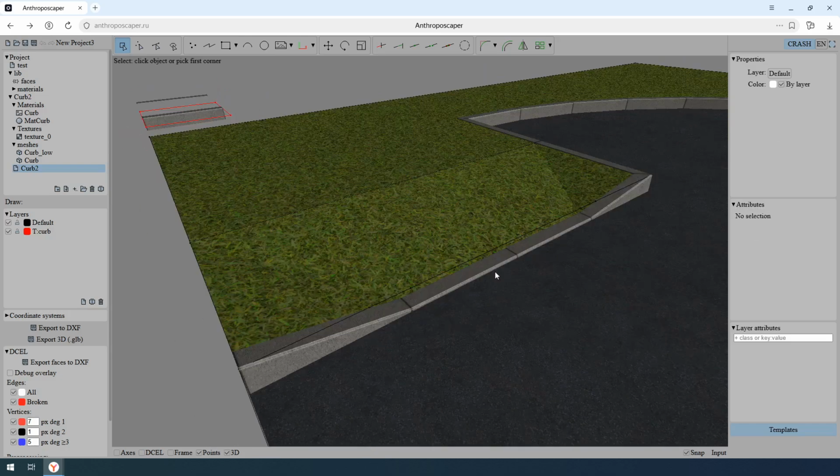One more touch, this time about lighting. Let's look closely at the spot where the descent meets the flat part of the grass. There's a sharp shading boundary there. A clear break in brightness at the edge. The geometry really does break at an angle here, and the shading of the two areas differs, hence the hard seam. You can smooth this without touching the geometry itself.